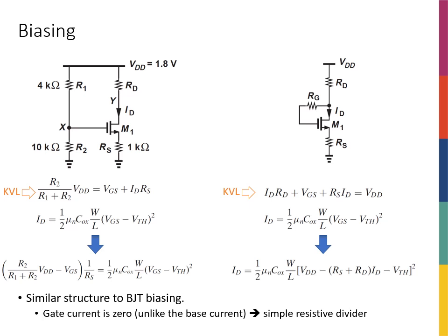Okay, so before talking about the amplifiers, it's actually good to have a little bit of a discussion, although brief, about biasing. The discussion is very similar to what we did with BJT transistors. We know we need biasing simply because if I take a MOSFET and connect the signal source to the gate of the MOSFET, and if this signal source, let's call it Vin, is, let's say, a small sinusoidal with an amplitude of like 1 millivolt, right?